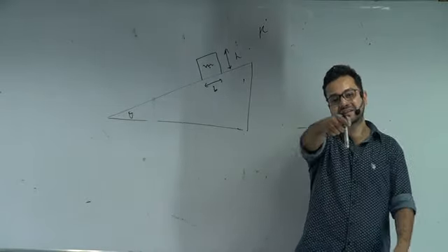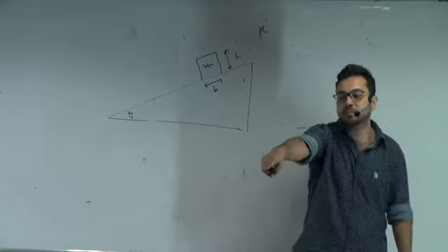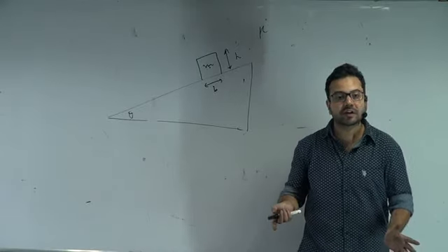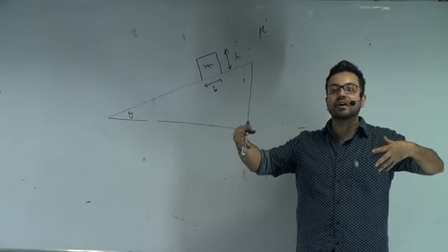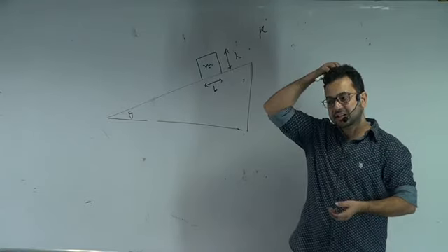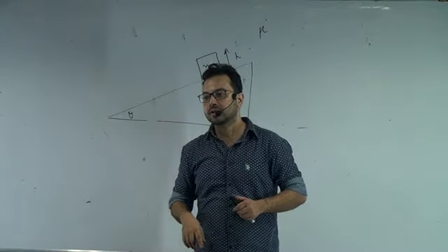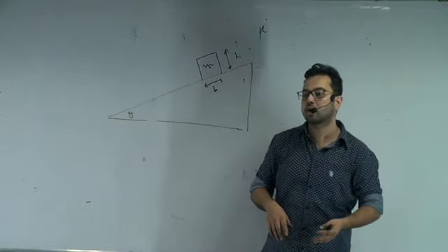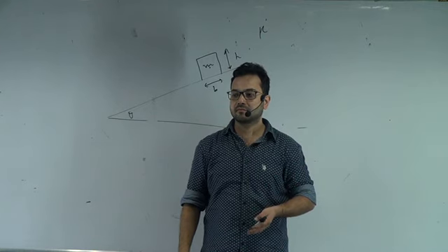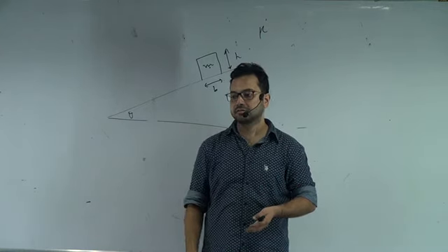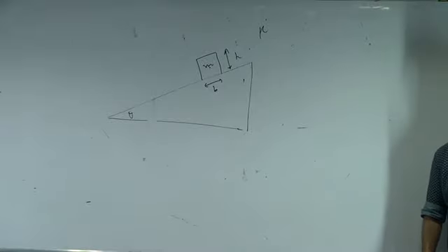Okay, so in that eraser that you were trying to move, what happened? It toppled. Why? And this book did not topple. Why? Coefficient of friction. Because that has a larger coefficient of friction. So if the coefficient of friction is larger, it will have a greater tendency to topple. Next, it will also depend upon the dimension. If you use that bottle, it toppled. Now keep it like that. Let's see what happens. It slides first. So what does it depend upon? The dimensions also.